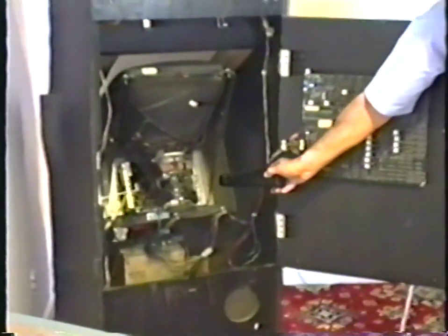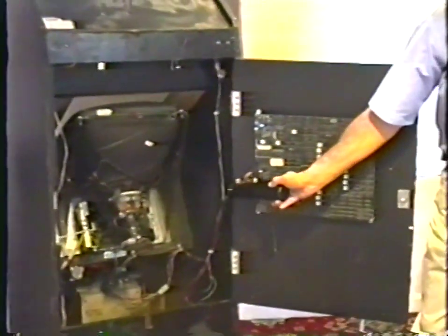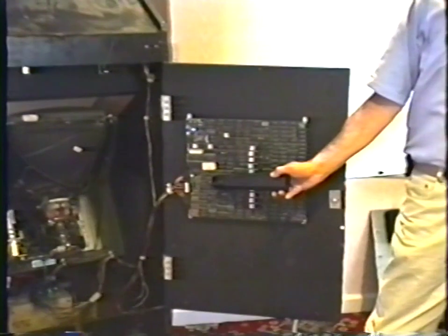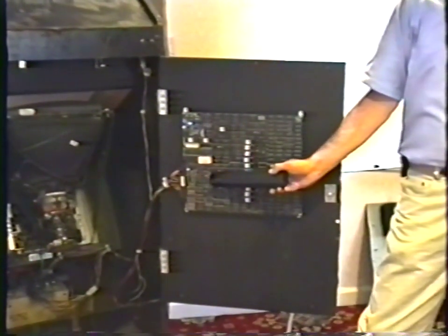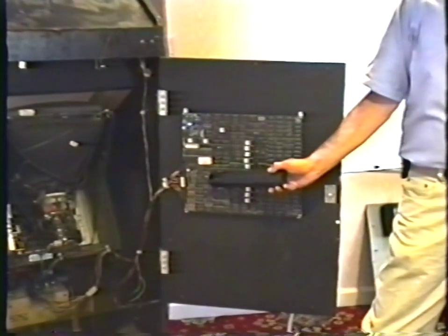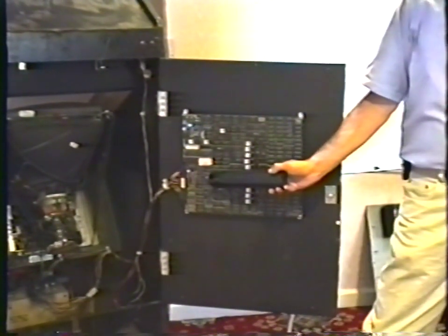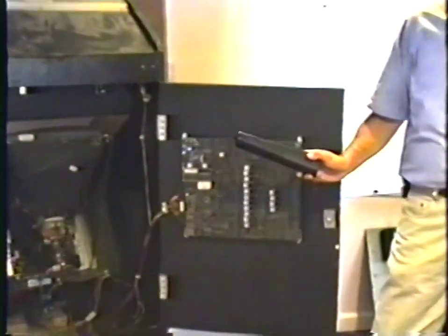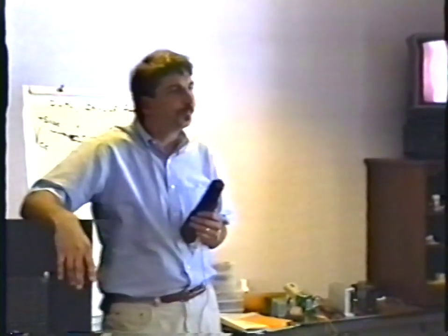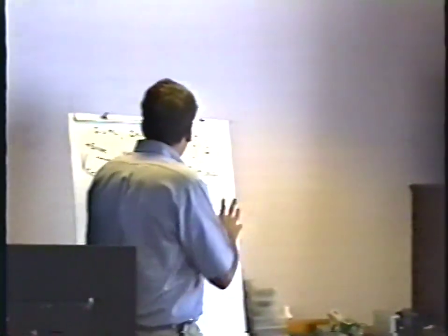By the time the current gets up here, through this wire, and over here to the logic board, maybe it's only 4.9 volts on the board. SkyShark's a perfect example of it. This game doesn't even work well at 5 volts. 5.1, perfect. But I've had them at 4.95, and they freeze up, they shut down, all kinds of weird things happen. So I always set it to 5.1 volts on the board.